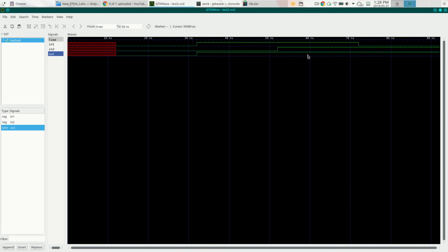So one of the buzzwords here is rapid prototyping, right? We just completely changed from an AND gate to an OR gate and it took about 45 seconds to rebuild the circuit, compile it, execute it, get up some timing diagrams. And if you build a circuit and it doesn't work quite right, you've got timing information, you've got output that you're printing, usually it's pretty straightforward to figure out where the problem is, or put in more display statements to narrow it down. And, oh, I meant to do B and I did Q instead, right? Go and change your code, redevelop it, compile, simulate, look at the output.